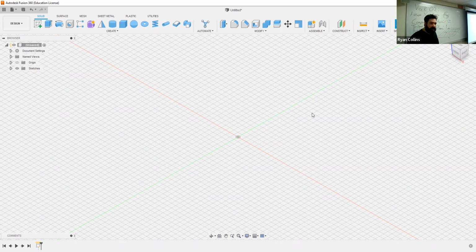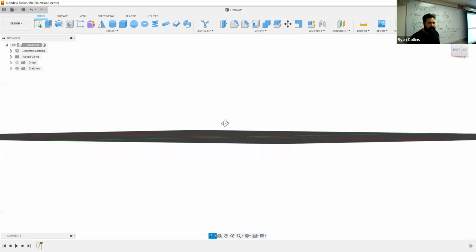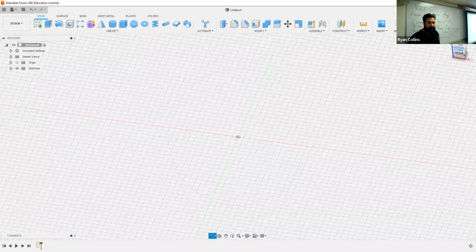To navigate as well, going down to the center bottom, this is how you can navigate without a mouse and a wheel. From the left, you see the orbit tool. I click that, and now my cursor has rotating arrows in a circle, going up and around from left to right, side to side. Now I can click and drag around, the same thing I could do by clicking and dragging the view cube. To get out of that, hit escape. Escape is basically the get-out-of-the-current-tool key for everything.